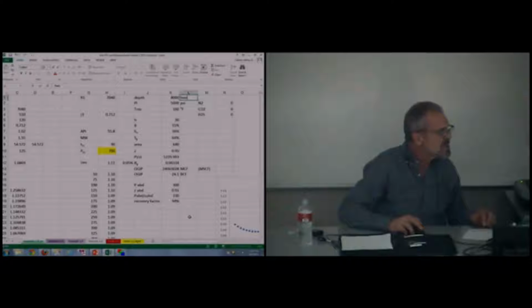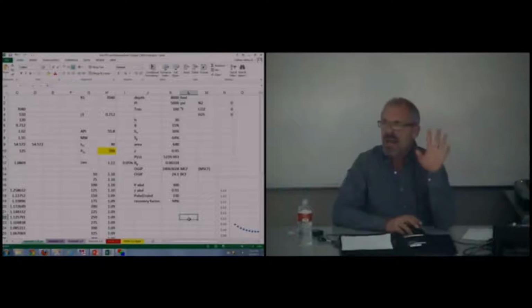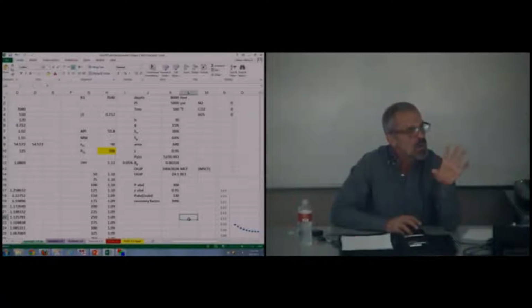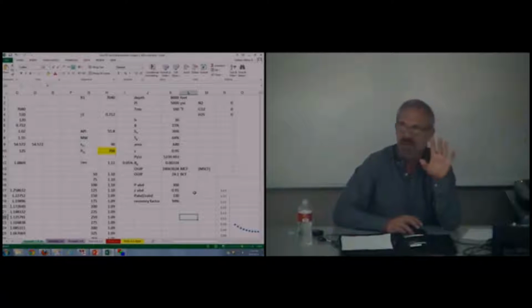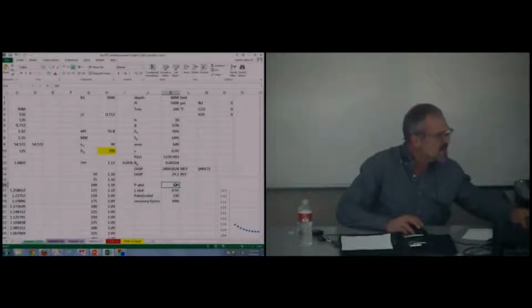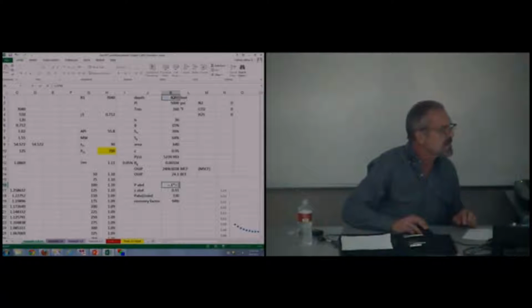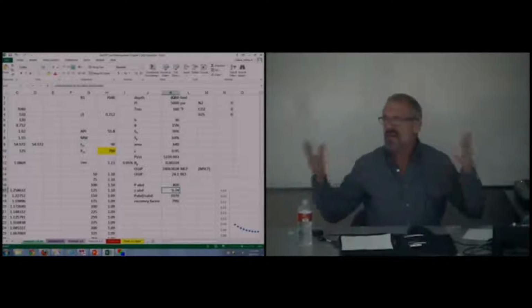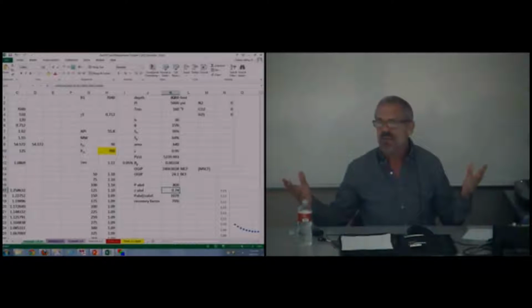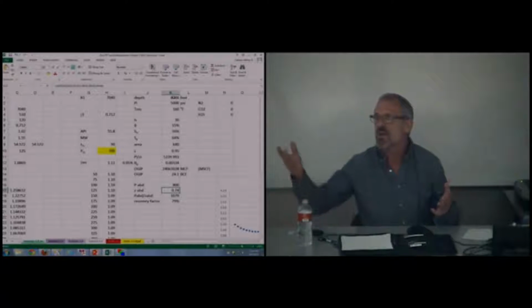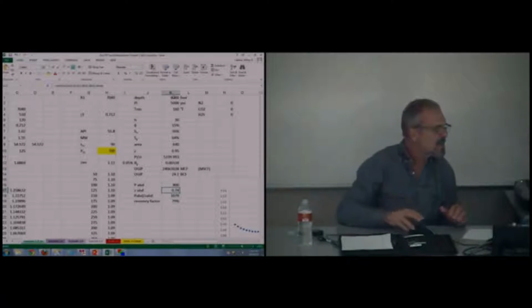Using a gas gradient of 0.1 psi per foot, zero surface pressure would give us 0.1 times our depth. So we're already up to 800 psi. That's with no friction or flow rate and no line pressure.